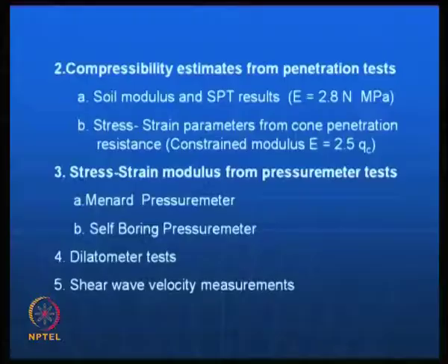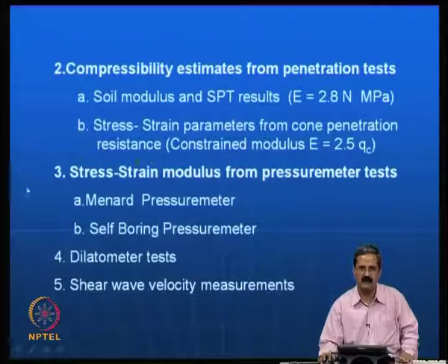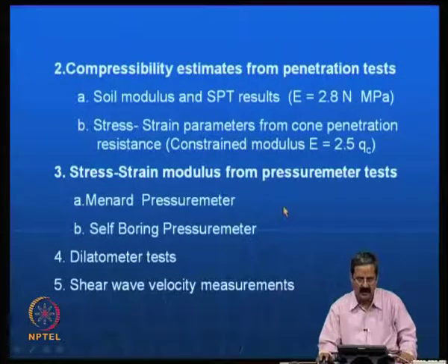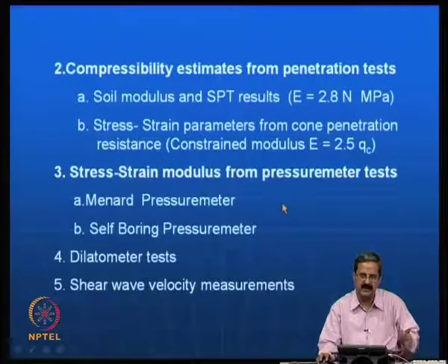So, there are two types of equipment here, one is called Menard's pressure meter and the other one is a self boring pressure meter. Actually, the Menard's pressure meter is a very standard one which was developed in France, which people have used extensively, and it has some parameters. You get Young's modulus, you get limit pressure, which is related to bearing capacity of soils.